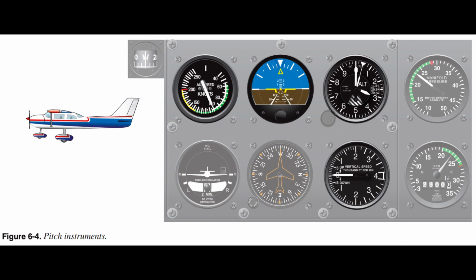Pitch control is controlling the rotation of the aircraft about the lateral axis by movement of the elevators. After interpreting the pitch attitude from the proper flight instruments, exert control pressures to affect the desired pitch attitude with reference to the horizon. These instruments include the attitude indicator, altimeter, VSI, and airspeed indicator. Figure 6.4. The attitude indicator displays a direct indication of the aircraft's pitch attitude, while the other pitch attitude control instruments indirectly indicate the pitch attitude of the aircraft. Attitude indicator.